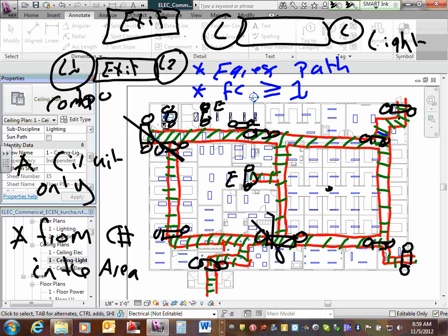Can I have thumbs up, Chad? Do you understand why you have to grab this fixture now and circuit it from the circuit that feeds this area? Same thing for this one. You pick these from the circuit that feeds that particular area. Everybody understand why? Because if you feed it from a separate circuit here, and you lose the power here because the circuit breaker tripped, this light will never come on.